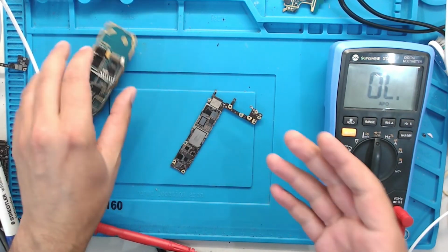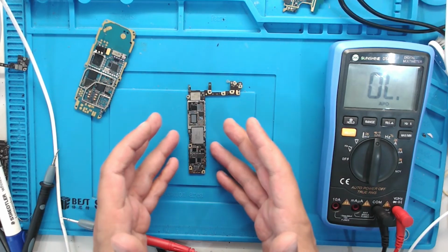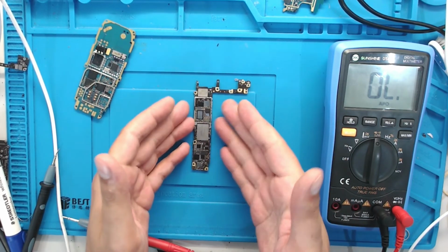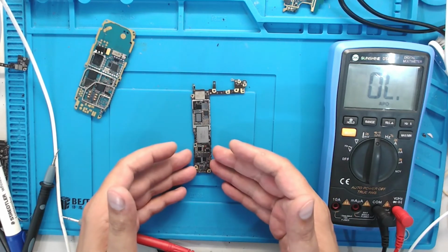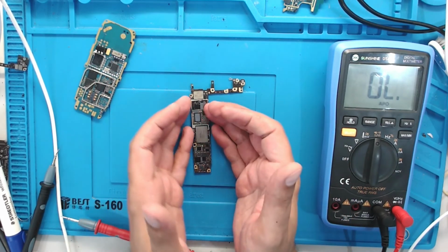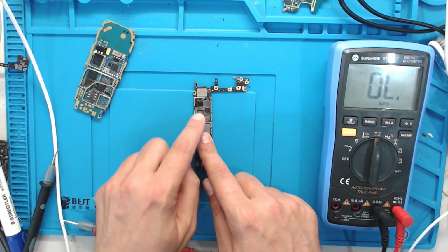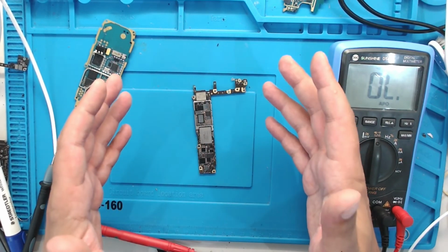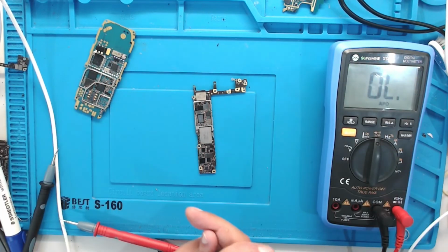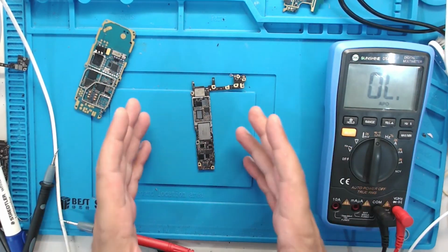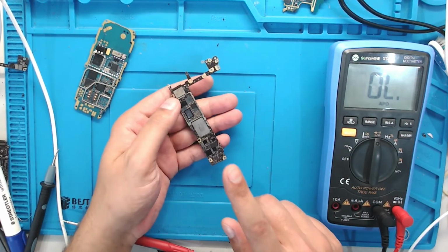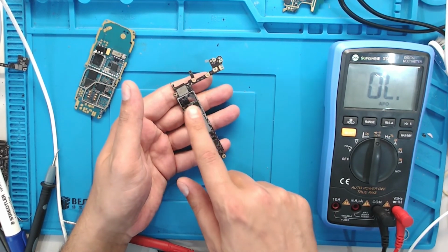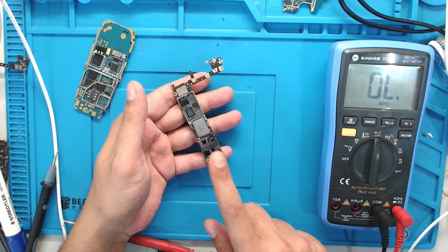And why do we need to know whether it has two sides or one side? Because suppose you bring the 4 volts voltage to this mainboard, but around the power management unit you find 3.5 volts. Usually, if the battery has 4 volts, you need to find 4 volts in here, but this voltage is lower than the battery voltage.